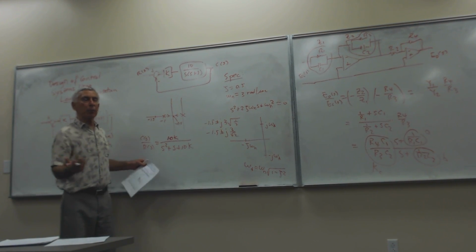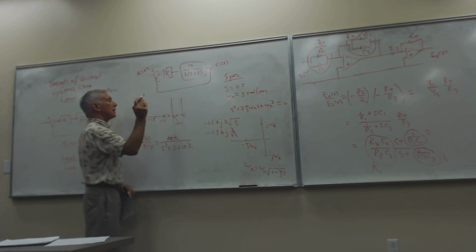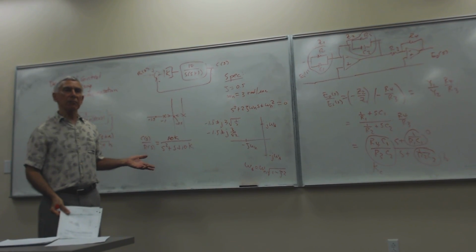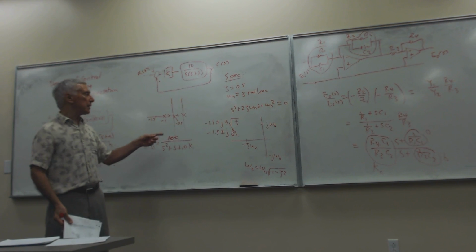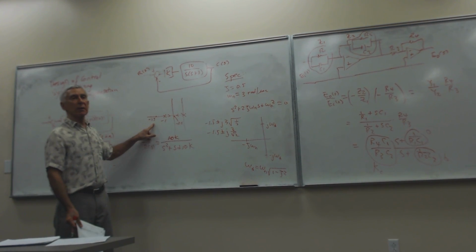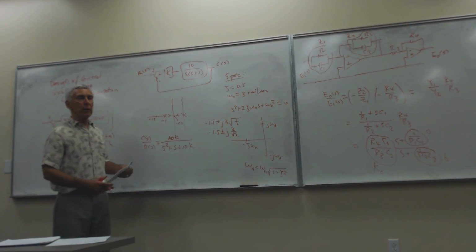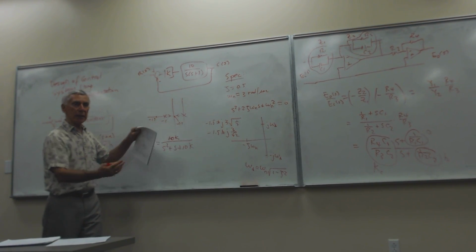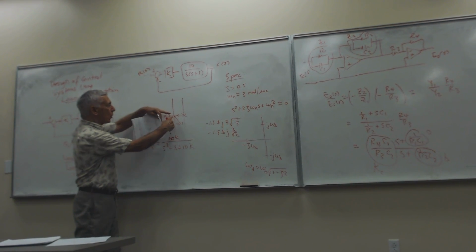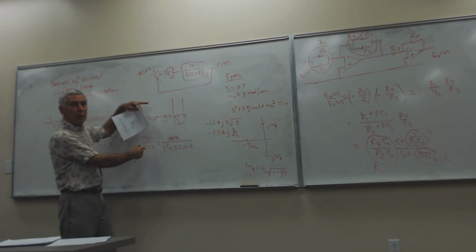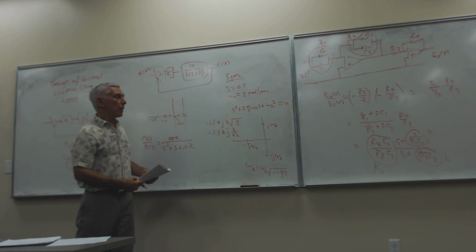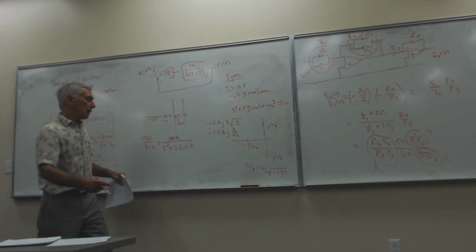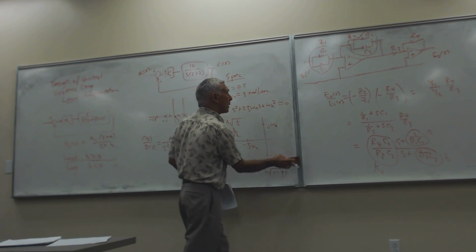And you see, with pure gain compensation, like here, there's no way to satisfy that specification because the real component will never be minus 1.5. So what we'll do is use the lead compensator to attract that root locus. The 0 of the lead compensator will attract that root locus. So we can redraw it.